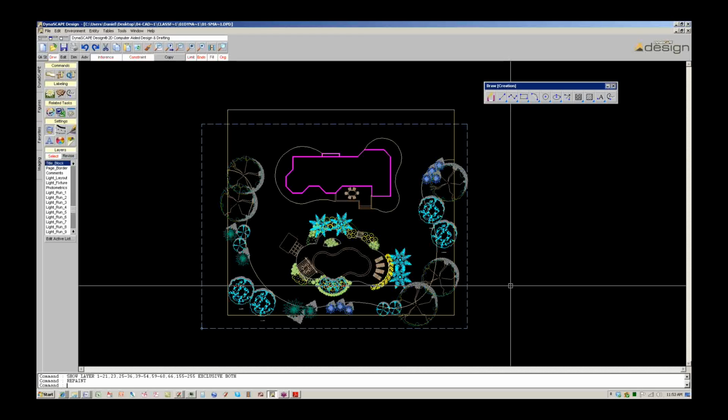I know this is the easy part, really, and let me elaborate on that a little bit. I've done this process from AutoCAD and Vectorworks to SketchUp, and AutoCAD is terrible going from AutoCAD to SketchUp. It requires a lot of cleanup to convert that AutoCAD file so it's not a mess when you bring it into SketchUp. Vectorworks has similarities to DynaSCAPE, which makes it easier. To date, I have not seen a program go to SketchUp as well as DynaSCAPE does.